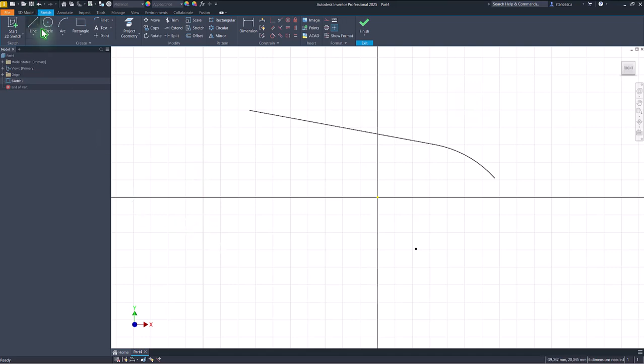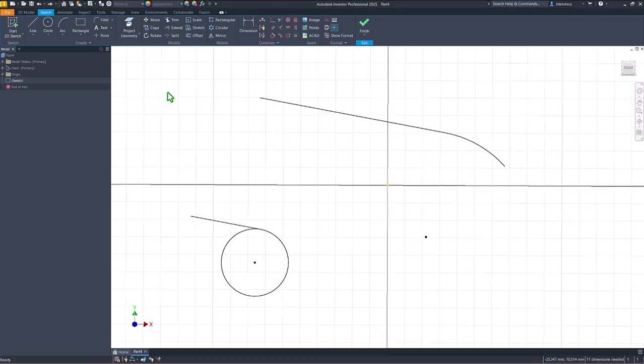Then, if you draw a circle and you start a line from the circle by keeping pressed the left button of the mouse, you can draw a tangent. To go in the other direction of the tangents, you have to go through the starting point. You see, I go to the right or through that point to the left. If you start a line from a circle and you go outside, you obtain a perpendicular on the circle. These are circle line variants.